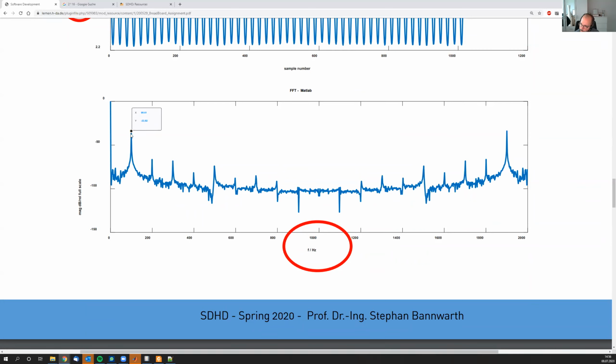At this frequency, we had a sine wave, okay? We can see this very clearly here, and we can also see which amplitude this sine wave had. This is the y-axis, in this scale this would be decibel again. And from here we could see that our amplification was minus 33.92 decibel. Okay, thank you.